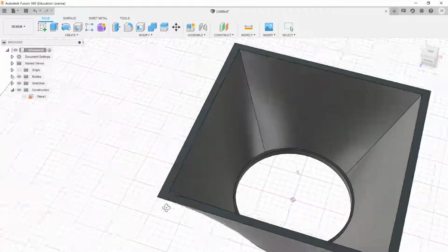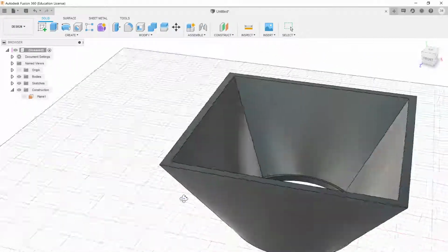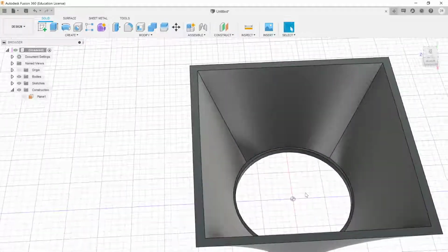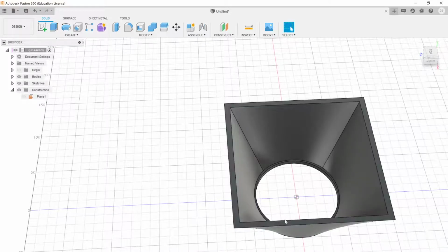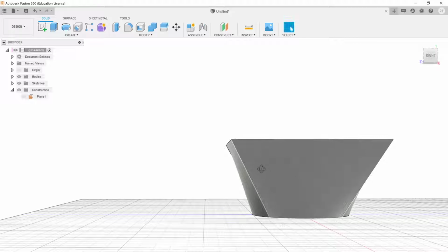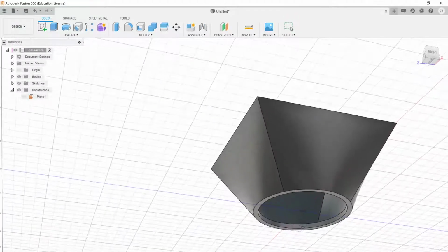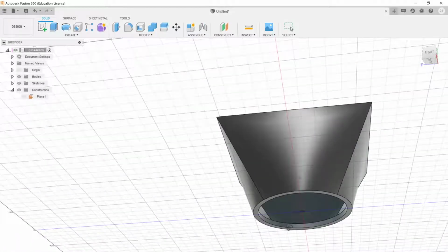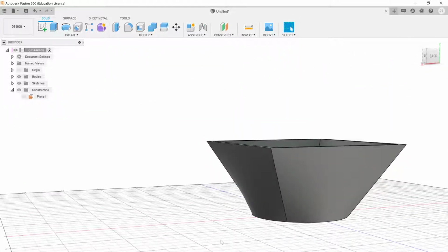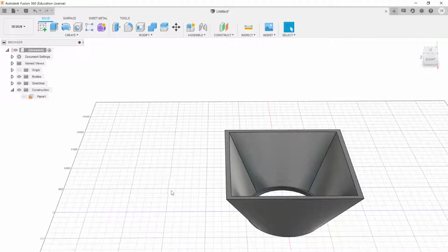We have a part that is very funnel-like. Obviously, if we made it longer and thinner, it would be an even better funnel. But the idea is that it is kind of like a bin that things catch into and then fall down through, and we've made it a pretty shape. And it's exotic in that it's not perfectly square. That roundedness is blended smoothly, and the curves are made for us, which is very convenient. So this is the Loft tool. This is a pretty useful tool to have.